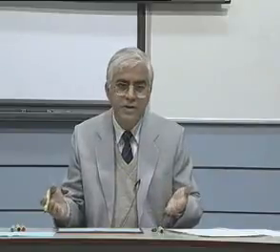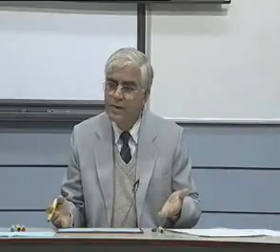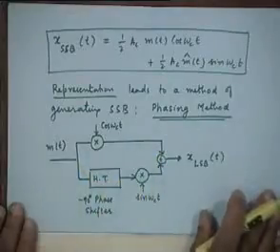You can think of a very simple circuit consisting of only resistance and capacitance to do that, right. In fact, an ideal capacitance would produce a 90-degree phase shift, right. But to realize it for a band of frequencies is not so easy, over the entire band. Same constant 90-degree phase shift.